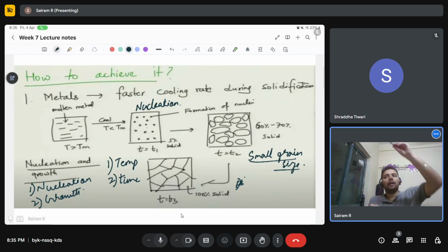No, no. From the molten metal, let's say I'm melting some aluminum alloy or some other alloy, taking it to a temperature of 1600 degrees. If I go to 1600 degrees, even steel, iron is going to melt. So let's say I have 1000 degrees. From 1000, I'm going to be continuously cooling it to room temperature or probably below that. My microstructure is going to depend on my cooling rate rather than the temperature at which it is cooling.